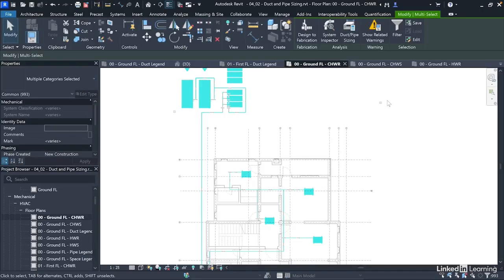And when you're done, you might still need to select the pipe segments and change their sizes to standard commercial sizes. While you're doing all that, always look at your system properties browser to make sure that the velocity is within range. So that's it. You can now size the ducts and pipes in your projects based on defined constraints. In the following videos, we will still explore even more systems analysis tools in Revit.